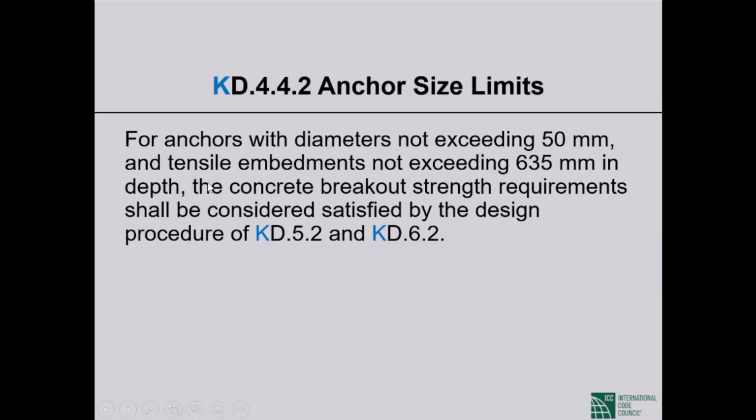Those are limitations coming out of Stuttgart tests. In Stuttgart, they did extensive anchor tests, but they did not go beyond 50 millimeter diameter anchors and they did not go beyond 635 millimeter embedment depth. So it was felt safe to put those limitations on. I did want to mention that to you.